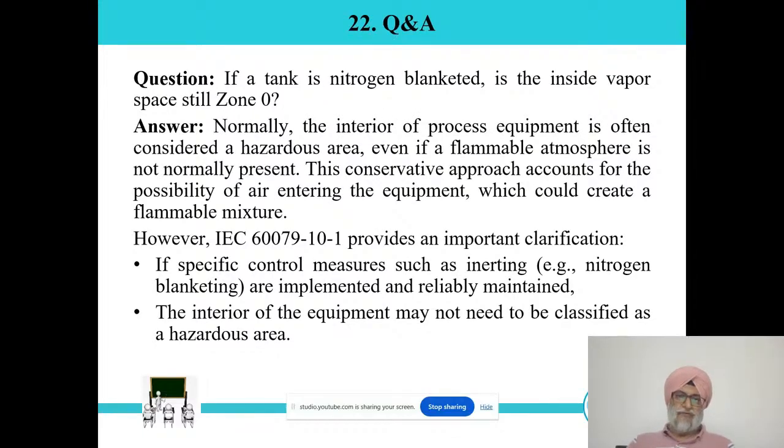Question number 22. If the tank is nitrogen blanketed, is the inside vapor space still zone 0? So basically, qualitatively, we can say no. But when we go into quantification, of course, we have to ensure that oxygen concentration is below the limiting oxygen concentration.